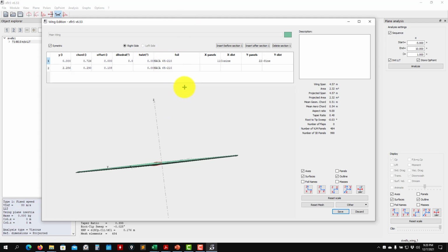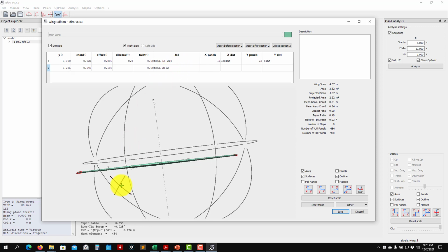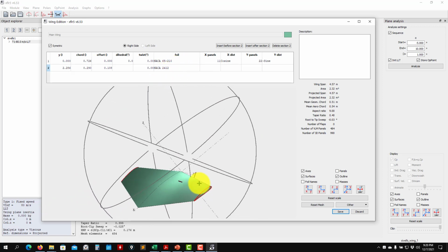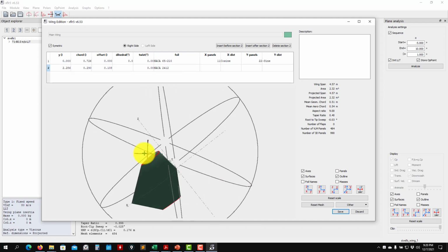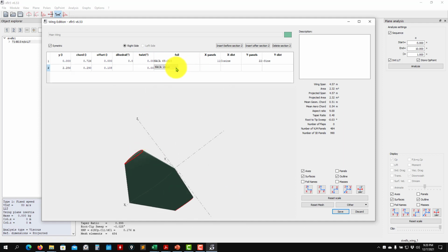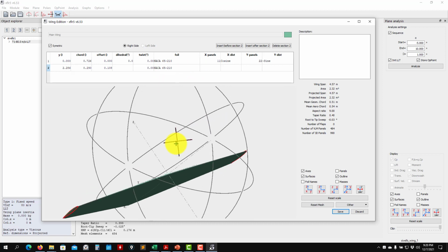So remember that previously we ran this, and here you access that information. For instance, we also have the NACA information. You can select it with no problem. See that I go here, and now we are adding aerodynamic twist. At the root you have this airfoil. At the tip, you have this airfoil, and all the information that you ran in XFLR is contained here automatically. Then the software will just do the interpolation and solve the problem. Let me go back here like this, and that's all.